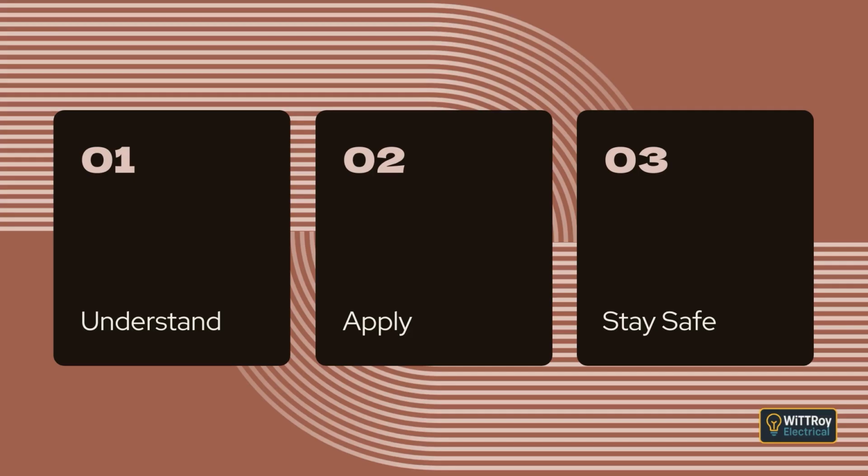This includes wiring on the surface of walls or ceilings, wiring between a floor and an area where people may gain access, wiring in ceiling spaces with access heights over 0.6 meters, wiring within 2 meters of any access point, and wiring under raised floors.